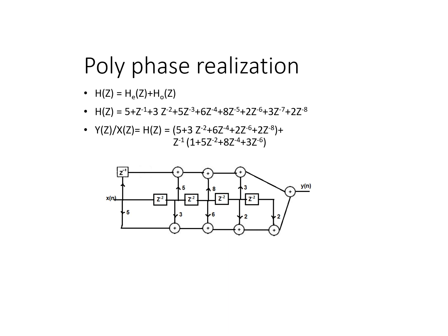Now both the polynomials will have the same powers of z as a coefficient. So here also z power minus 2, z power minus 4, z power minus 6, z power minus 8, like that. So we can take one delay, say z power minus 2, z power minus 2, z power minus 2, z power minus 2. So totally the maximum delay required here is z power minus 8. So 4 blocks are taken.